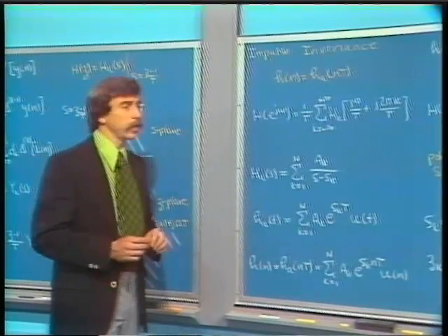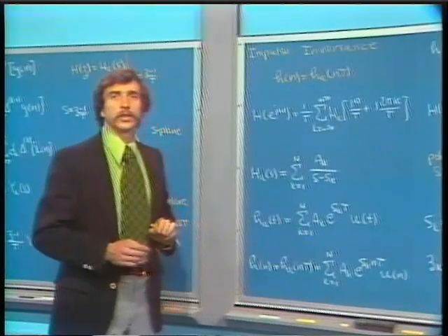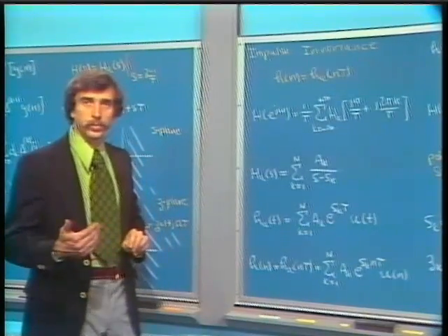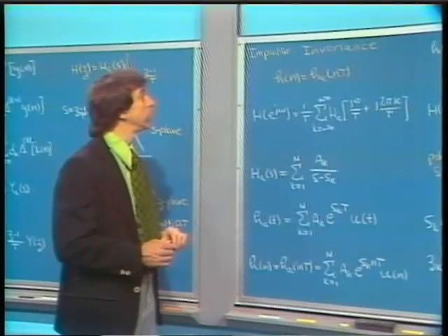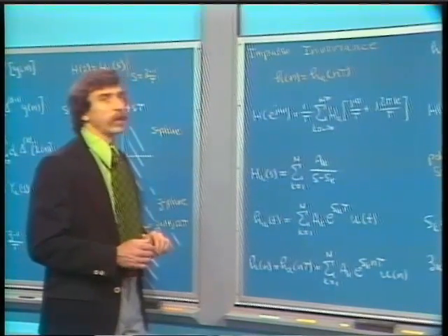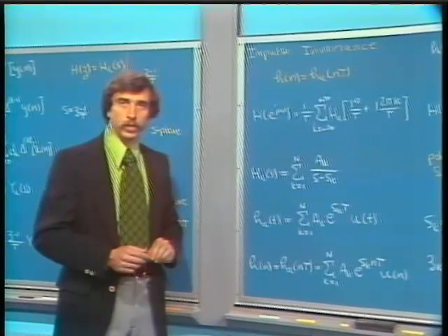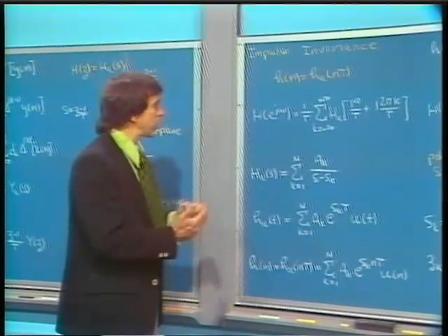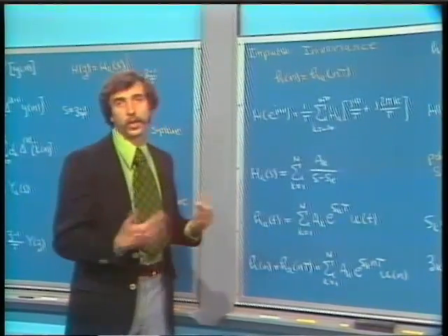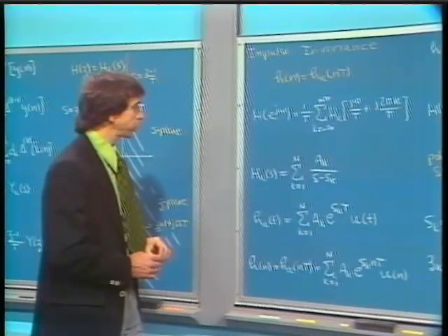It should be pointed out, incidentally, that impulse invariance doesn't imply step invariance, and you'll see this in the problems that you work through in the study guide. Impulse invariance does not imply step invariance, so if it was the step response characteristics that we wanted to preserve, then the technique here isn't what we would use. We would use a modified technique, which would be not impulse invariance, but step invariance.